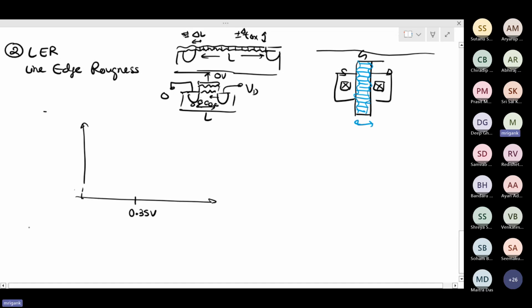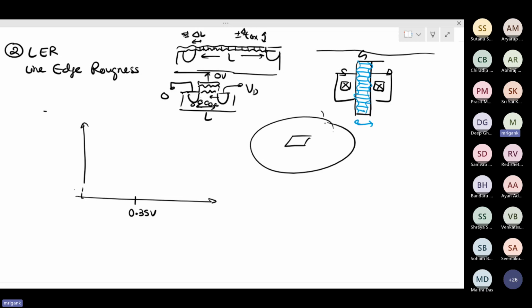But now, because of the random variation, on that particular chip that you took out from that big wafer, right? You cut this wafer into small chips. When you are on this chip, there are, suppose, 100 MOSFETs, maybe hundreds of thousands or maybe millions of MOSFETs, but assume that right now it is 100 MOSFETs. You measure the VT of each of these MOSFETs.